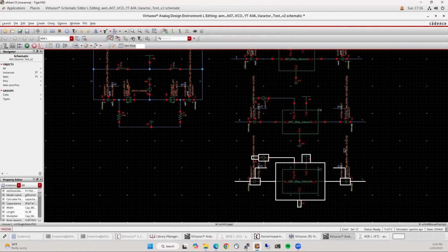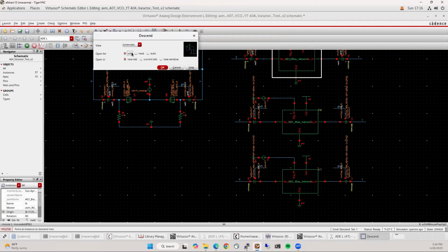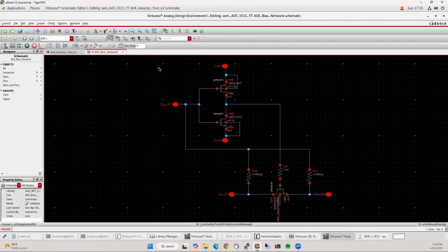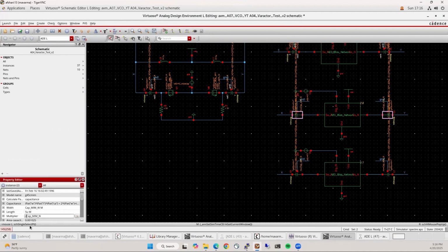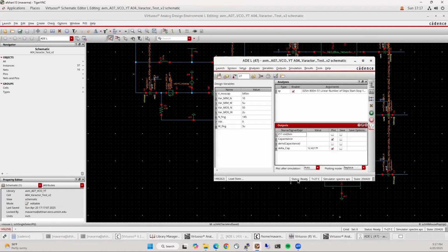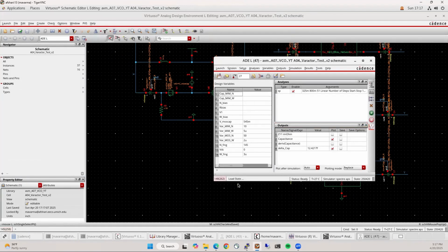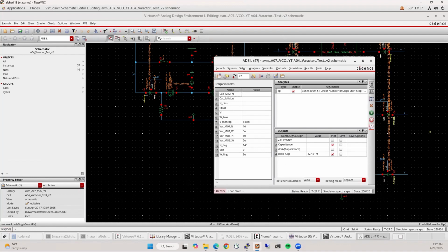I'm being a little bit lazy here and doing it this way. But now the problem becomes that I cannot change these for each of them, but you should actually scale these bias resistors for each of these bits. And so this is the first bit, second bit, third bit. So what I can do now is just say this is twice as large, and this is 4 times as large. Okay, that's it. So let's copy from here. And then we need to set values for these guys.